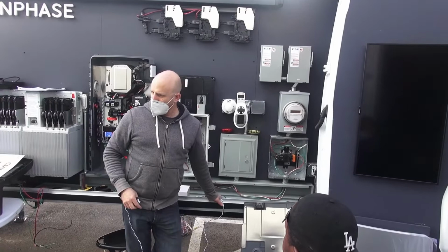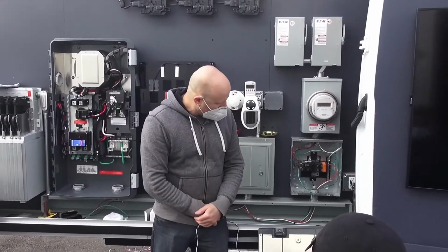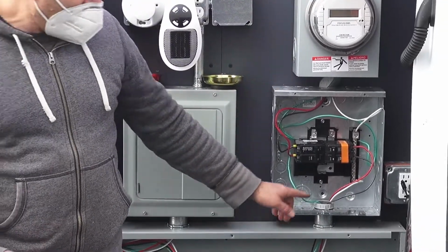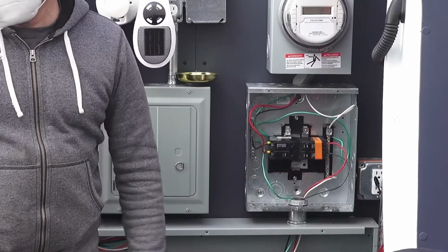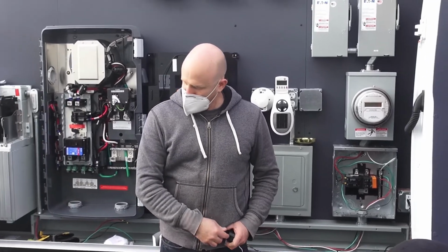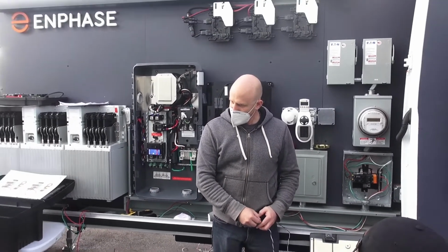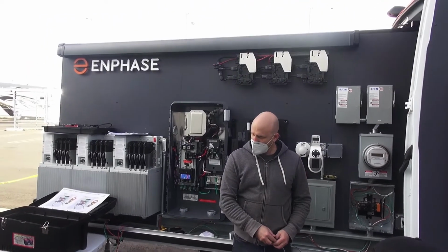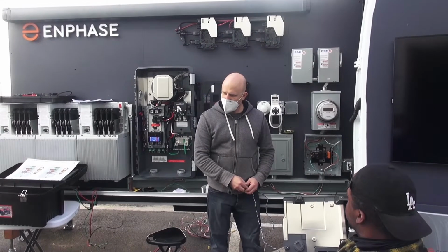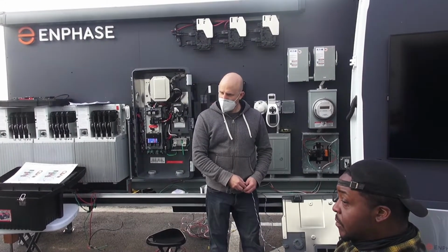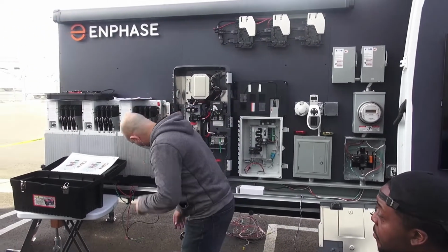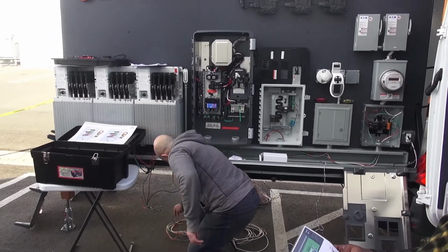And you guys already started to talk about it, right? But I want to make a point to you. If I just look at the colors here, making sure it's off, how do I know that these colors are correct? How do I know there's no mistakes somewhere in the wiring? You can measure it from the main lug, like the left one, we can test it with the voltmeter. If the voltmeter shows 0, it means the same. So you're going to measure the wire, right? If I heard you correctly? Voltmeter.